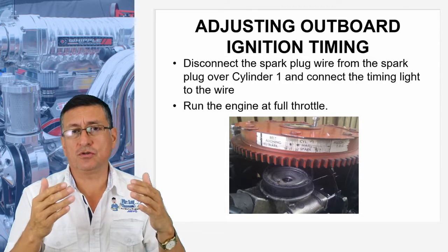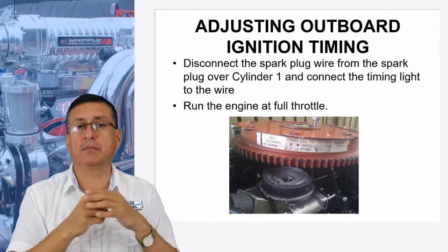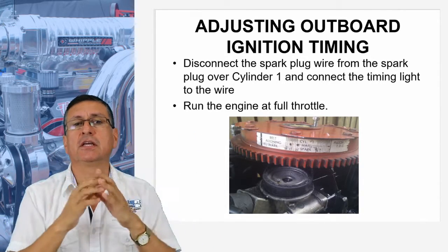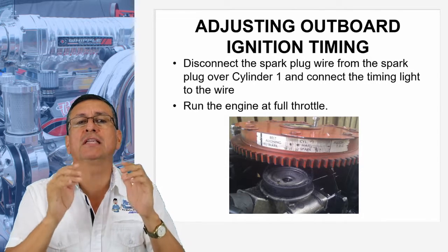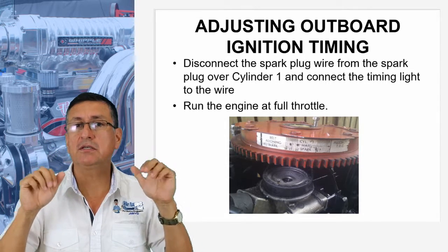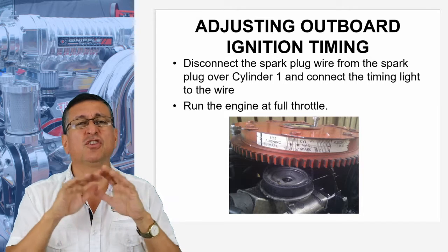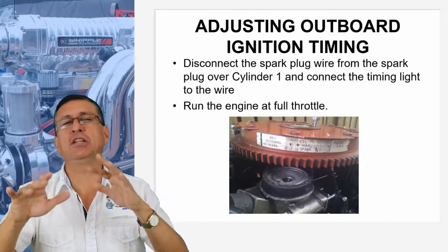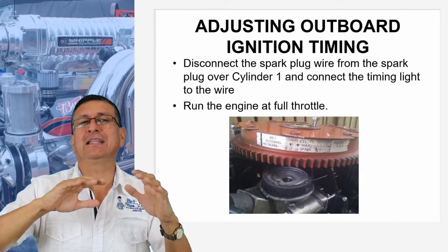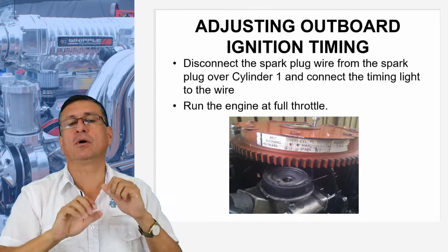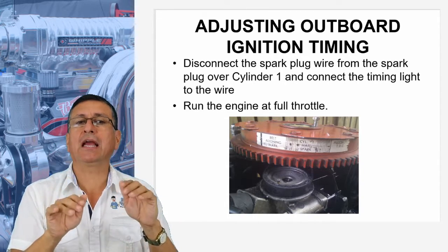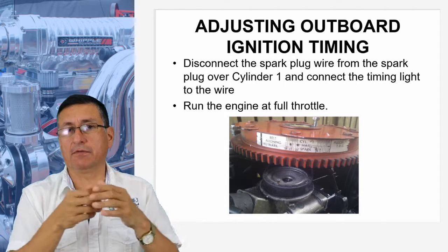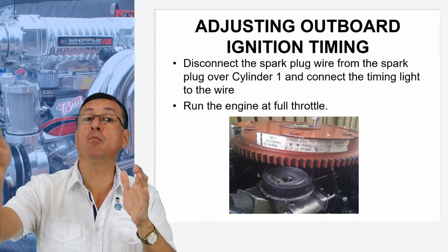In the new engines with computer, with ECM and fully electronics, those engines adjust the timing automatically in the computer. It's not mechanical. You don't need to think about the timing for wide open throttle because the computer calibrates the timing by itself. Exactly the same for outboards.